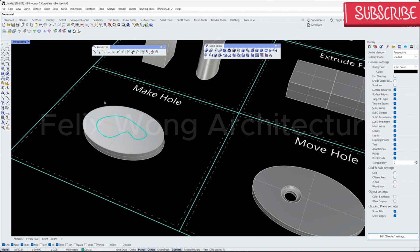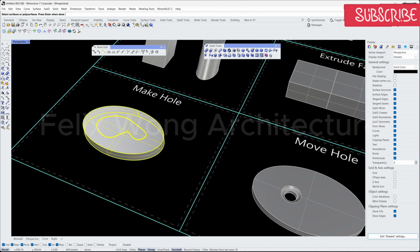Choose Make Hole to create a customized hole. Select a planar and closed curve. Press Enter. Select the poly surface. Press Enter. Then drag your mouse to specify the depth.